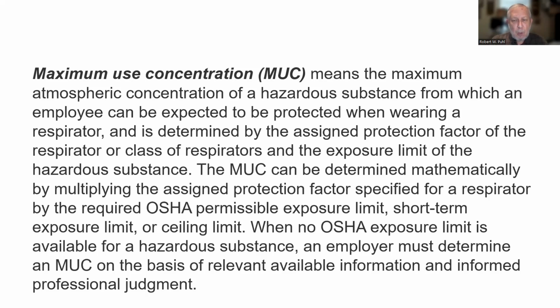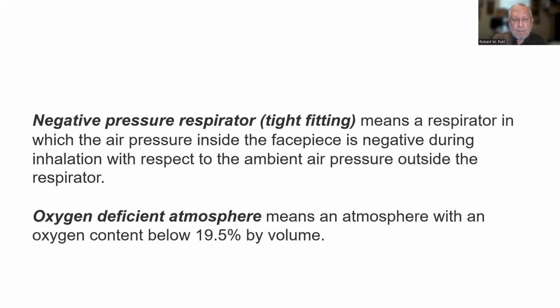When no OSHA exposure limit is available for a hazardous substance, an employer must determine an MUC on the basis of relevant available information and informed professional judgment. So they're leaving that kind of wide open if they haven't covered it already. So that's what a maximum use concentration is. Negative pressure respirator, tight fitting, means a respirator in which the air pressure inside the face piece is negative during inhalation with respect to the ambient air pressure outside the respirator.